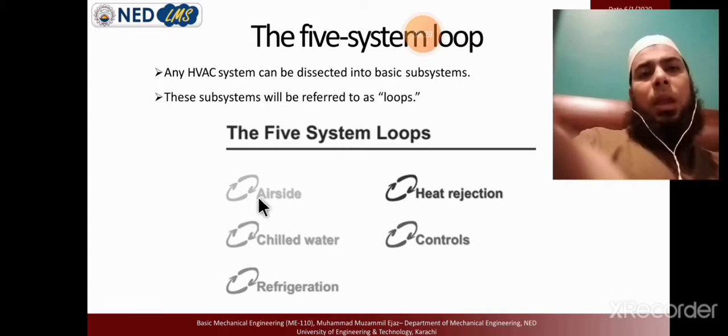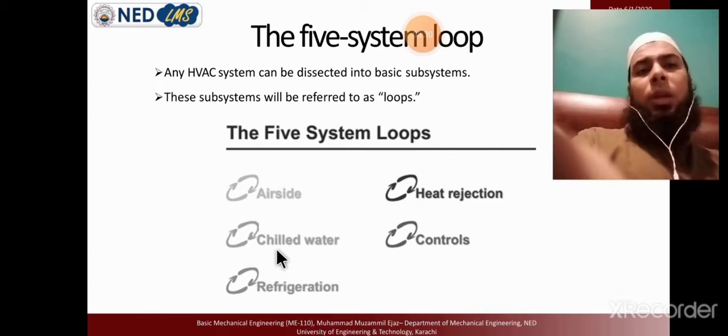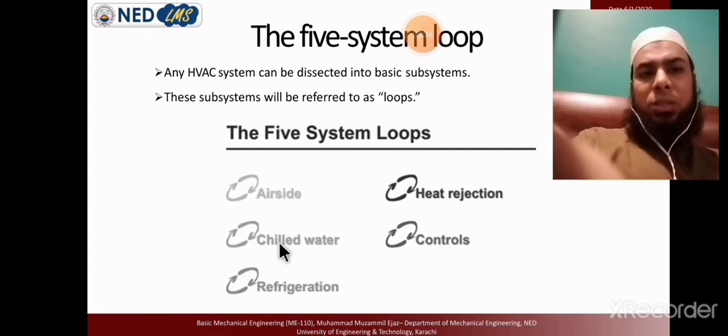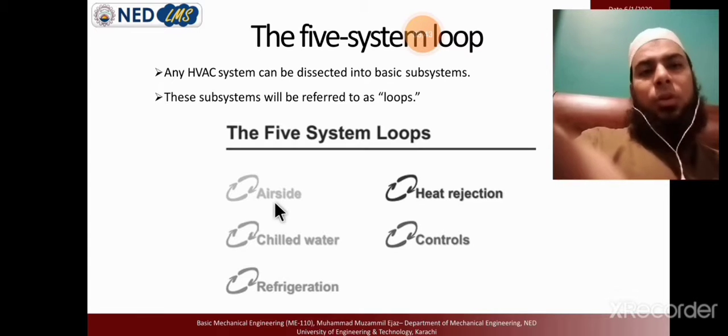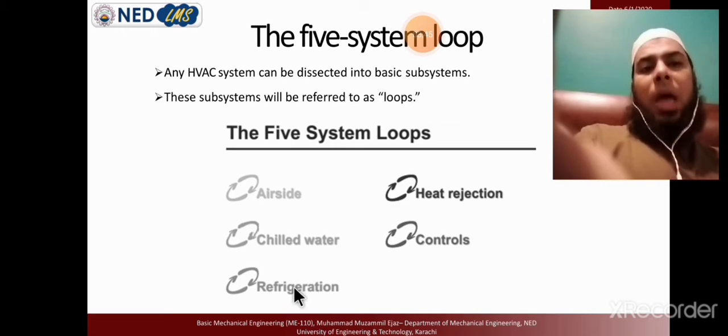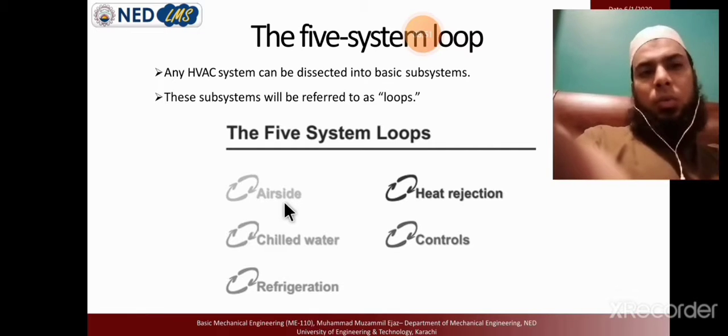Okay, now how is the air cooled? Either by chill water, where refrigeration cools the chill water and then the chill water cools the air, or the rooftop unit or package unit, where direct refrigerated cooling coils cool down the air side, just like your indoor unit or your room AC. But in commercial and office buildings, we have a very large refrigeration circuit.